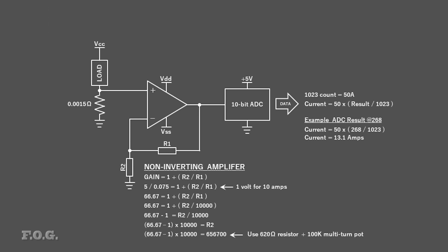And now for the caveats, because there are some possible issues with this design that you should be aware of. The first is, you need to give consideration to the sample frequency in relation to the frequency of the input signal. In other words, if the current signal is changing at a much higher frequency than you would be sampling at, then the measurement you are making might not be a good representation of the actual current.